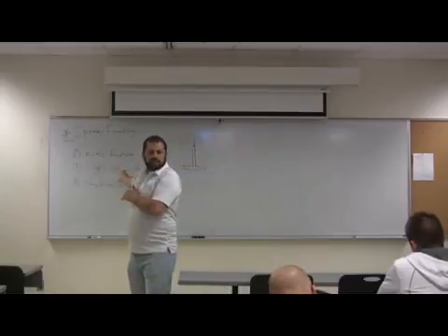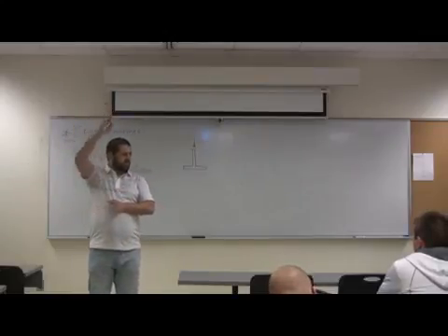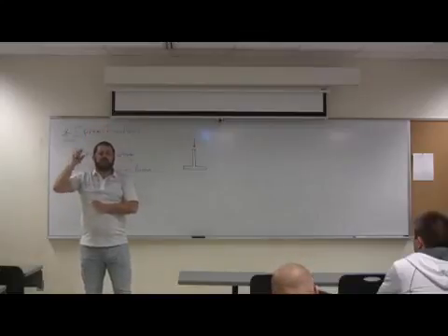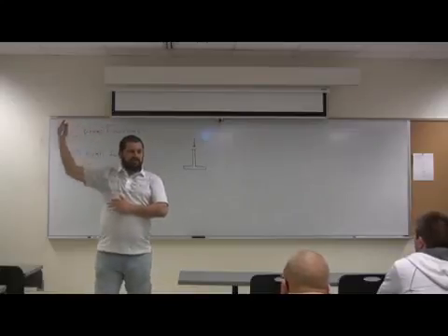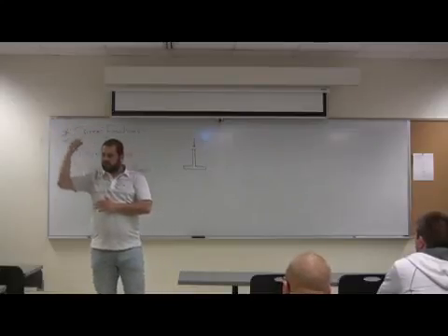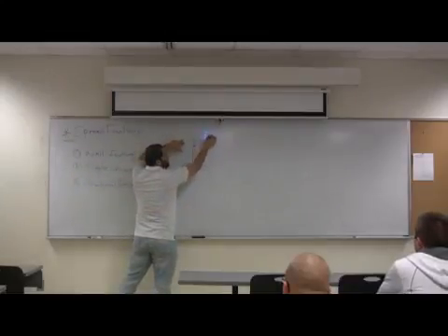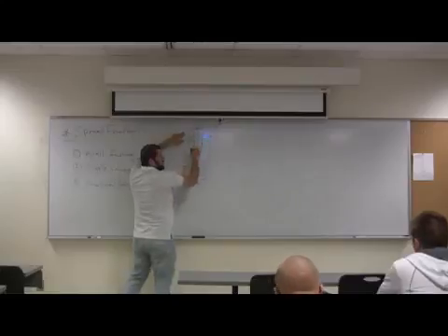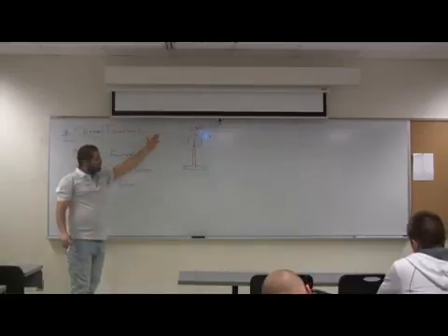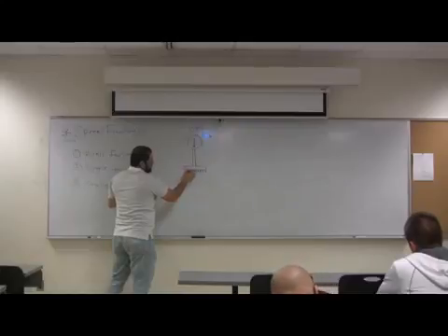In other words, the load on that wall will be the self weight for whatever number of floors on top of that wall. It means the slabs are resisted by beams, sometimes on the edge, because the walls are on the edge. They are carrying load, and we calculate the load per foot. So the load will be specified in kips per foot or kilonewton per meter, dead and live, and any other loading if there is any. This information will be given to you. This load will be resisted by a foundation like that, or the soil pressure.